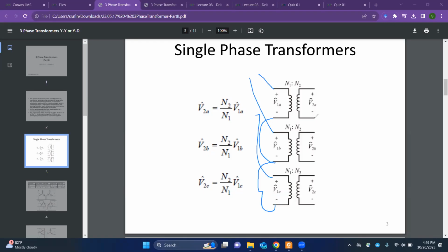If I want to do the same for the secondary side, I'll connect these two and I'll connect these two. So all have a junction point, and these three leads, the actual leads, will form another output. So that's for the Y connection. Those are my very poor drawing, but let's go for the next one.